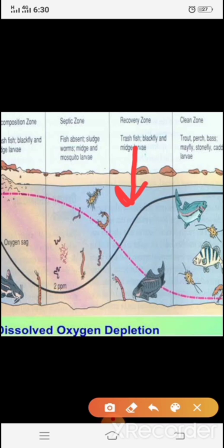First of all, this depletion is called deoxygenation, and this addition of oxygen from the surface is called reoxygenation. Because of this reoxygenation, this process is continuous, and you will see that it is getting nearer on the extreme end, and in this case the oxygen is being continuously added into the system.